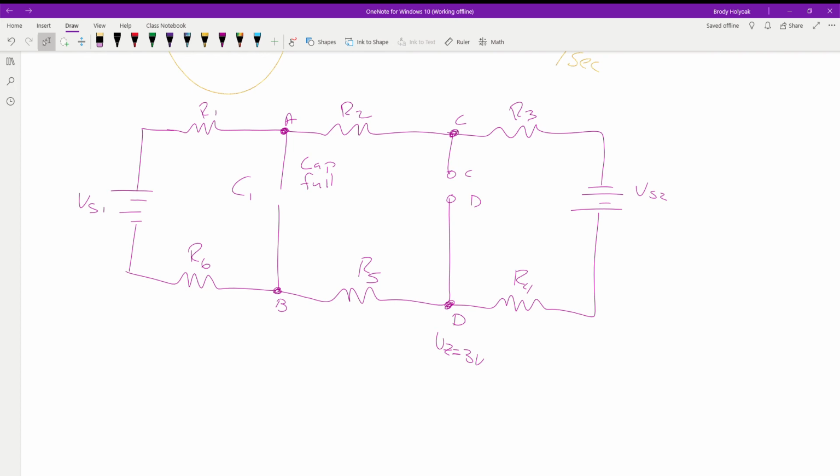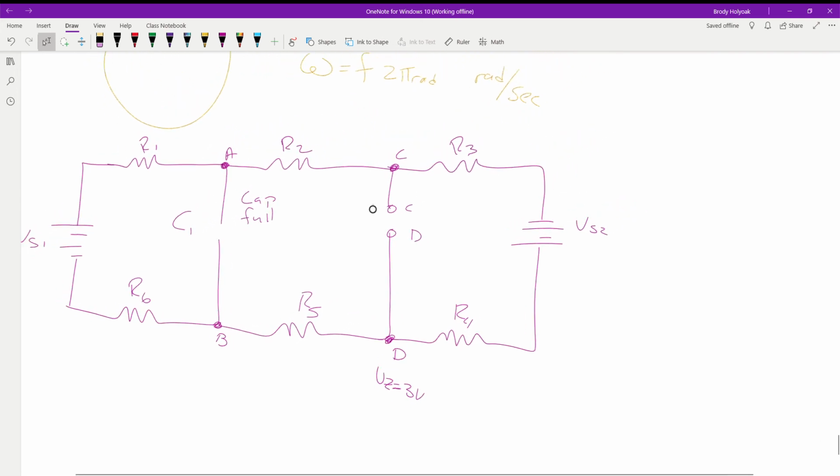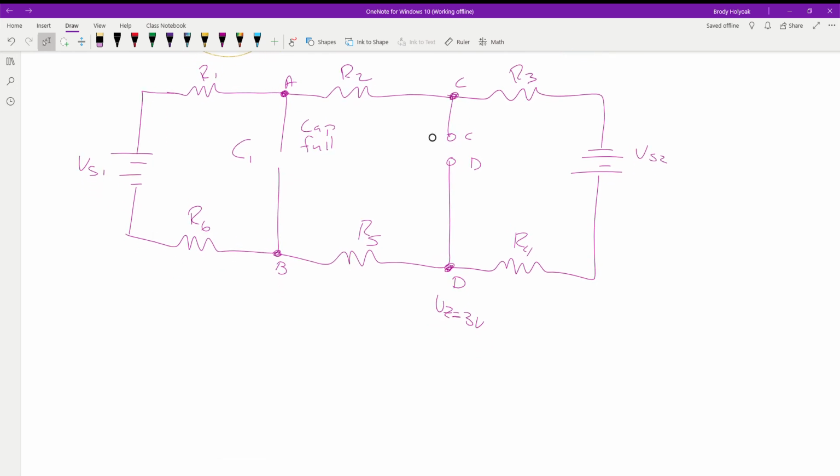Are they aiding or opposing each other? They're going to aid because you have negative turning into the positive. You have resistance in series. What's it going to do? It's going to add together. Now we can go through and find out what the voltages are with these two components removed and put them into the values and see what we get. Then the idea is we're going to literally go from point C to point D and determine, is this diode in forward or reverse bias?